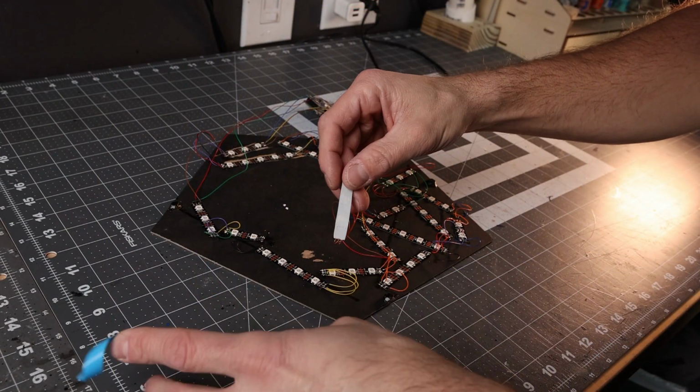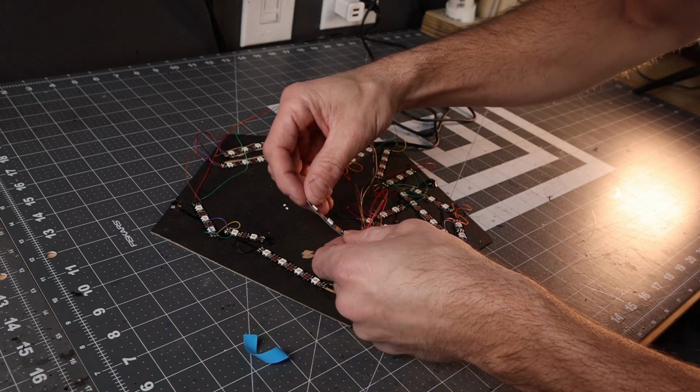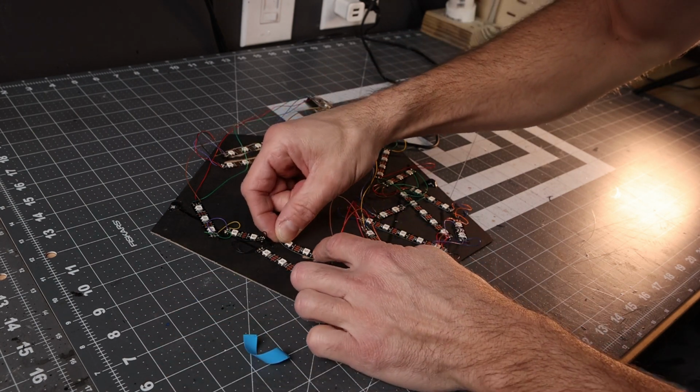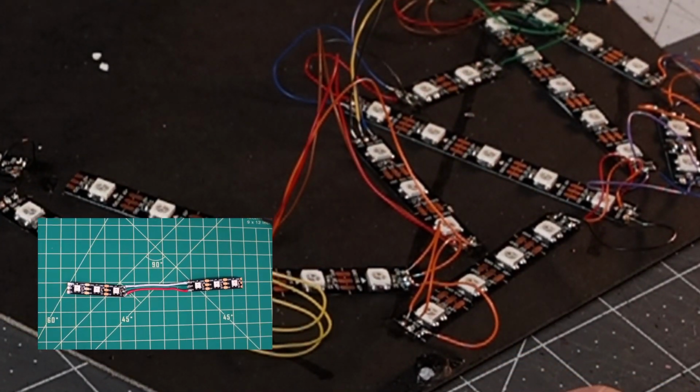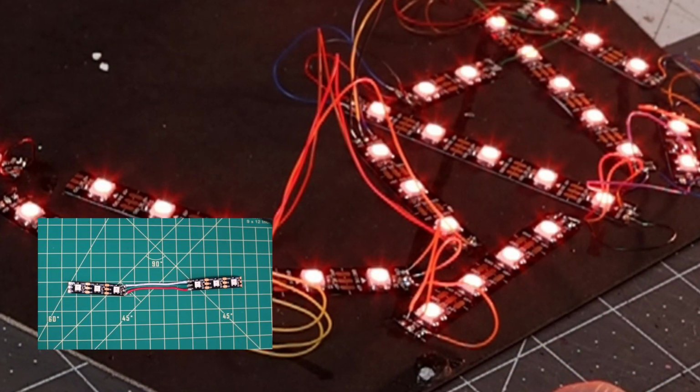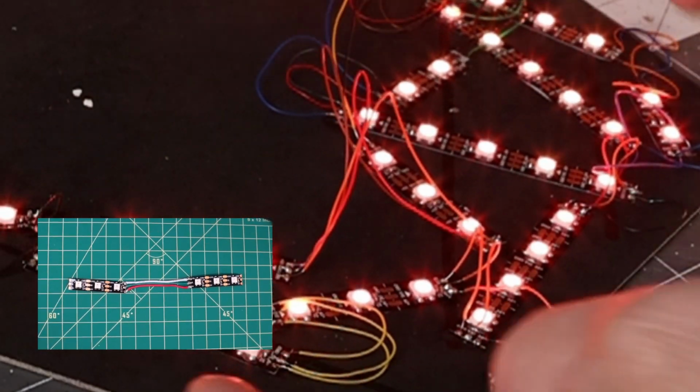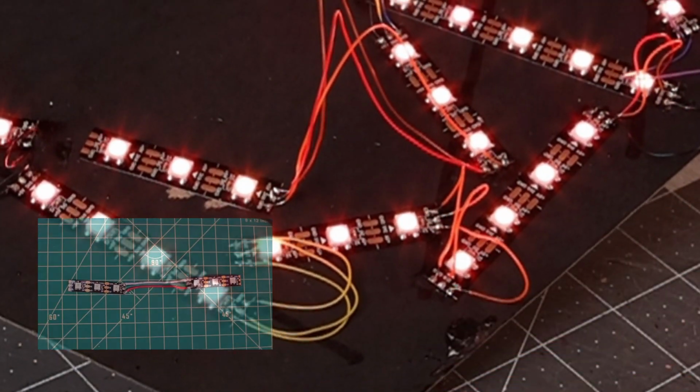Given the scale we're working at here for terrain and so on, you want to find one with as many LEDs as possible. When you put them on your terrain, you don't really want to put them in long straight lines. They will look awful, as John mentioned in one of his videos. So what you'll end up having to do is to cut them into 1 and 2 inch strips and then bond wires between them. 5 volts to 5 volts, ground to ground, and then data out from one to the data in of the next, so that you create one long daisy chain.